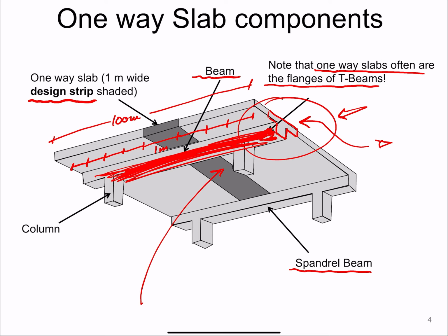So don't get surprised if you have to design, for example, in this case, the one-way slab, and we will see that that involves placing steel and other structural considerations. You design this slab, and then you design the beams, and then these T-beams, because those loads don't disappear. You say, well, the loads are being taken by the one-way slab. Well, who supports the one-way slab? The T-beams, and now they have to be designed for the loads that are tributary to each T-beam. So first design the slab, then design the T-beams. Get that force down.